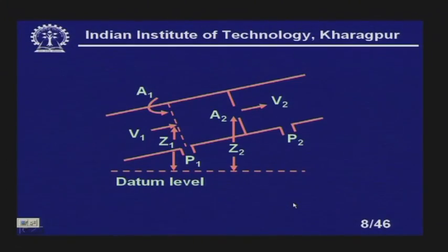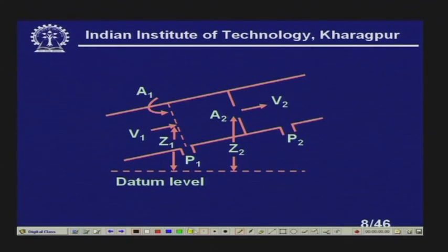Now, you see this is a typical schematic of the differential pressure flow meter. You see here, this is a pipe, liquid is flowing through this direction, it is coming out this direction, clear. And you see there is a restriction, in the form of an orifice. It is basically a circular plate, please note, with a concentric hole in the middle.